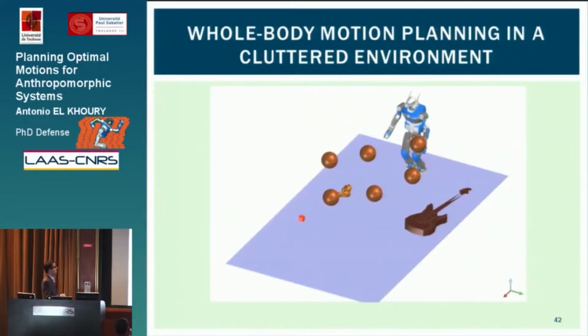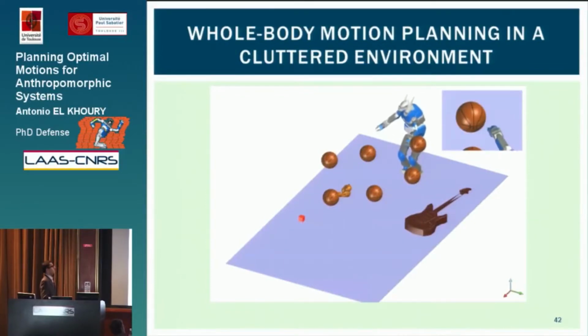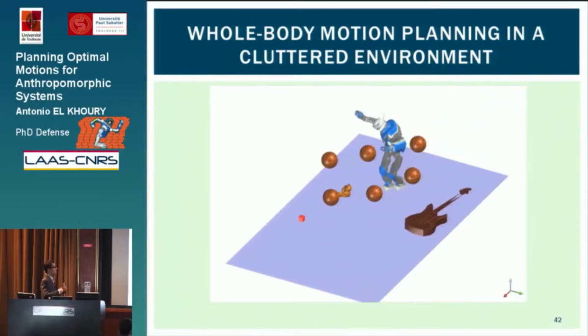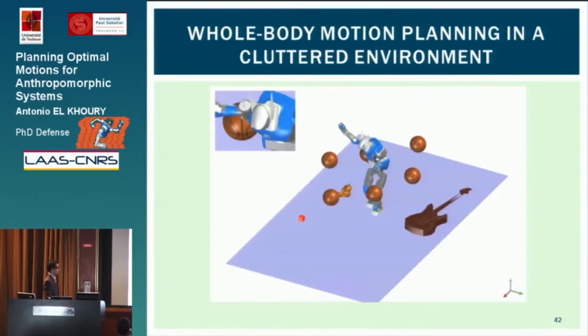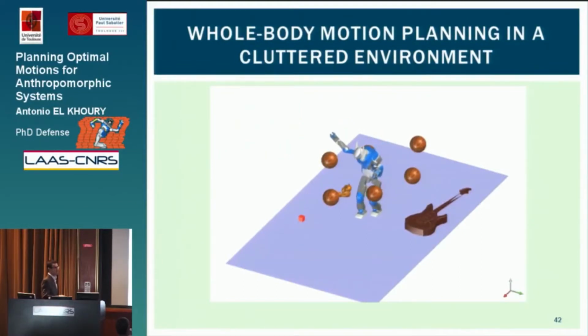And here is the same approach executed on the previous example, where we start with a sliding path and we obtain a sequence of stepping motions. As you can see here, when we are close to obstacles, we have small steps, whereas when the environment is not constrained, the robot executes what we call nominal walking. And when we reach again a new obstacle, there will be again small steps that will be executed to avoid collisions. And the nice thing is that this always works.